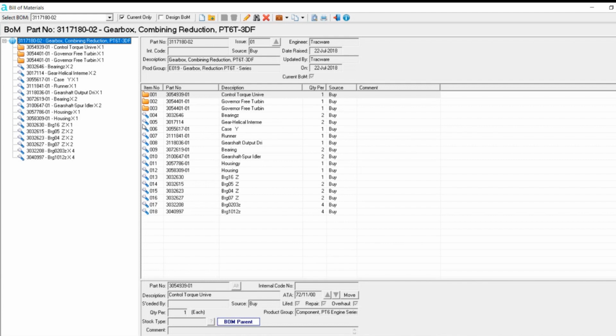So when you're building an aircraft, you start with your part masters. You can then build your BOMs. The aircraft management stuff will just basically ignore a lot of the parts. It's only really interested in anything that's a life limited component. So you could be doing both engine and component overhaul as well as aircraft management. And the BOM in that sense is multi-purpose. You can have a BOM which is there for the overhaul side of the business, but Aerotrac will also just pick out the life limited components purely for the continuing airworthiness side of things.